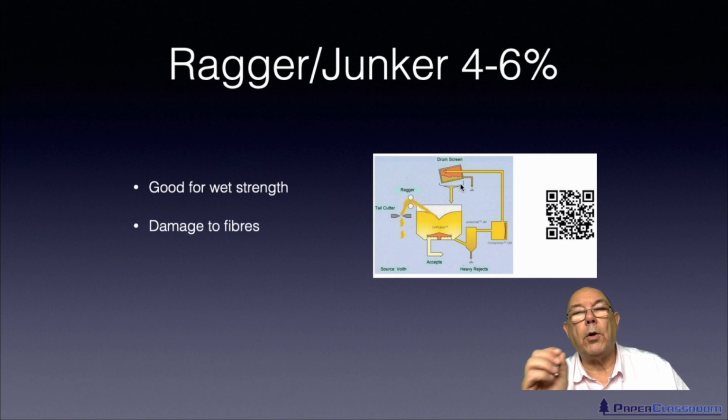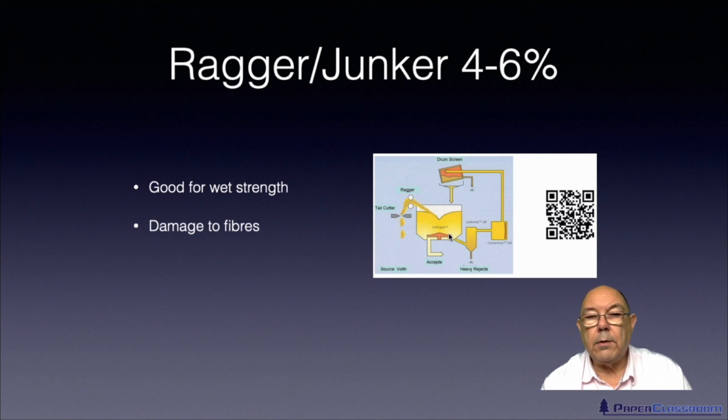All these small solid objects that are too light to settle down in here, then they'll be caught in this drum screen. They'll climb up the wall and then drop down and be caught in a skip or something like that. So that really takes care of hopefully the ragger junker.